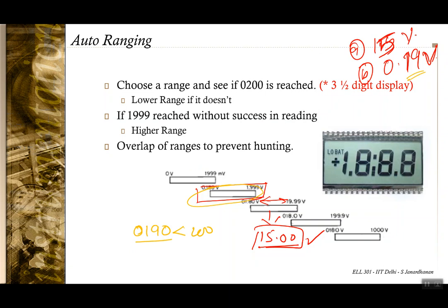Then the reading that you now get in a 4-digit display is, let us say, 1902, say this is 0.1902 volt. So all the 4 digits are now displayed. So it will have 0.190 volt or 190.0 millivolt. That is a display that you will see.